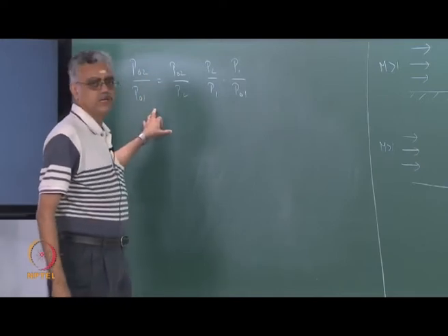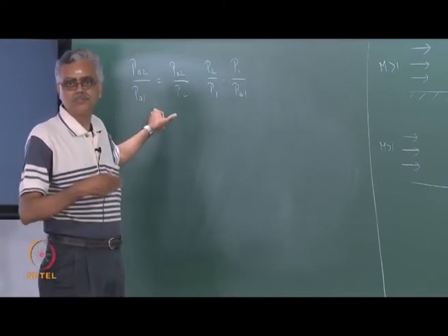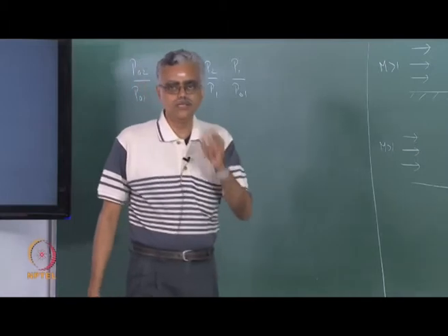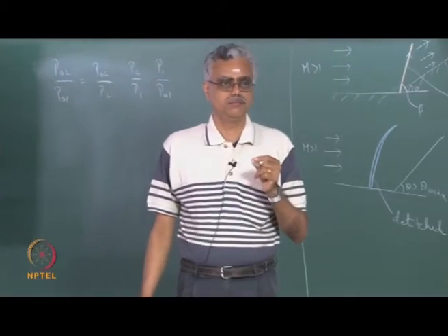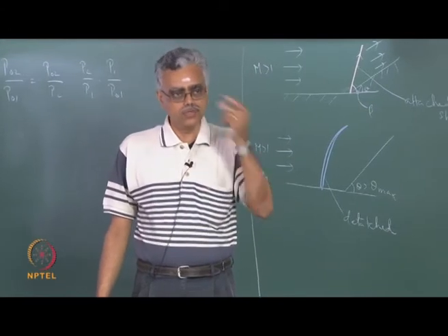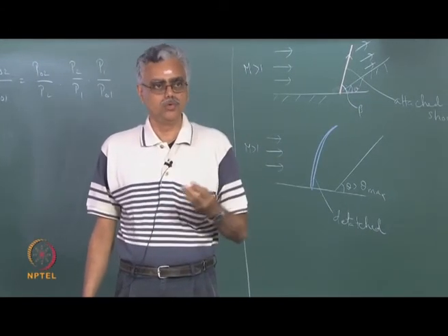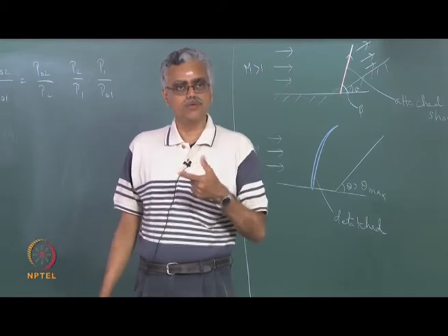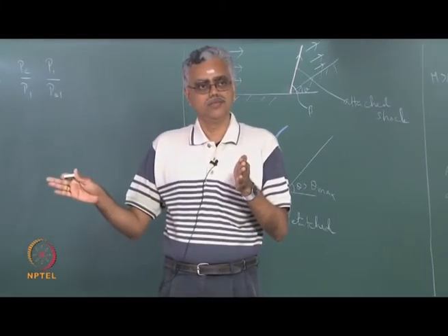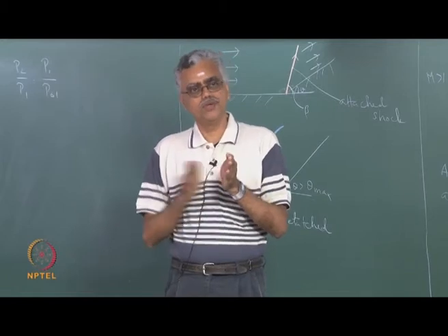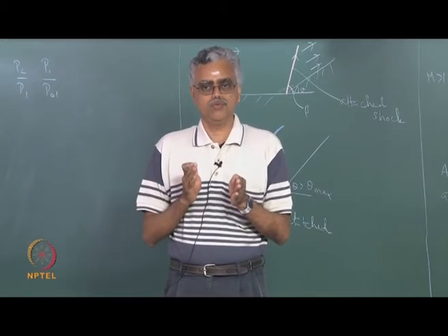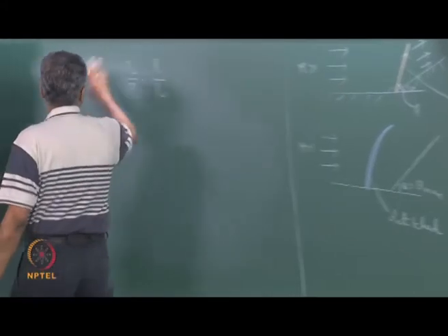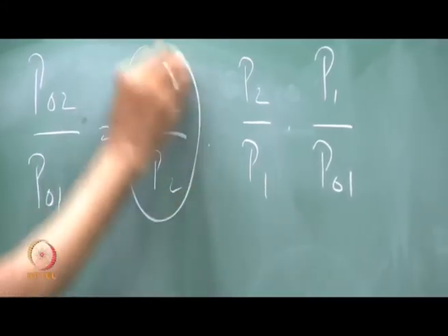when you remember, we said that for the normal component of the oblique shock wave, we can use the normal shock tables. Okay. So, you can use the normal shock tables only to retrieve static quantities, not stagnation quantities. So, you can use the normal shock table to get P2, T2, maybe rho 2, but not P02, because P02 is frame dependent, and in a normal shock wave, we are moving along with the shock wave. Whereas in the case of an oblique shock wave, we are not only moving along with the shock wave, but we are also moving along the shock wave, which means stagnation quantities cannot be retrieved from the normal shock table for these problems.